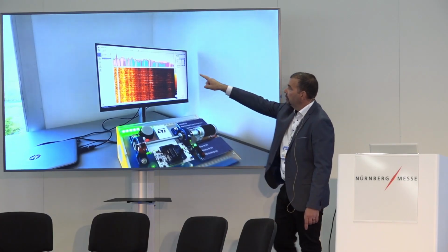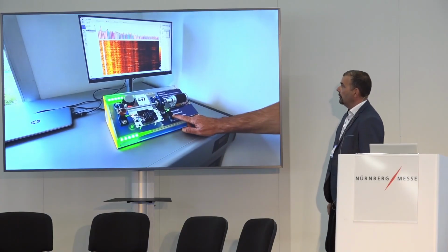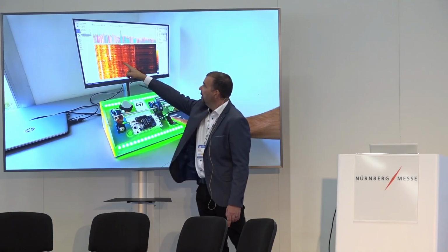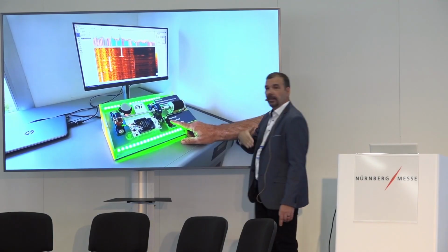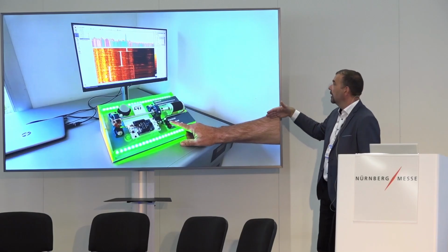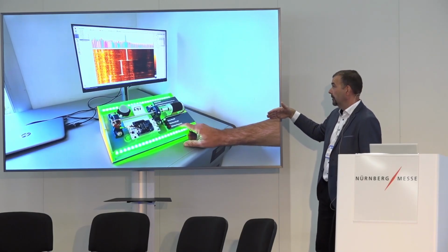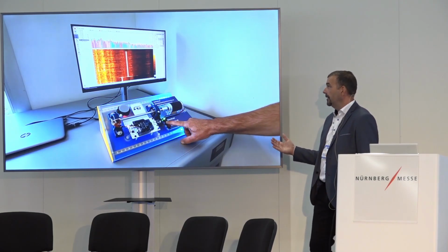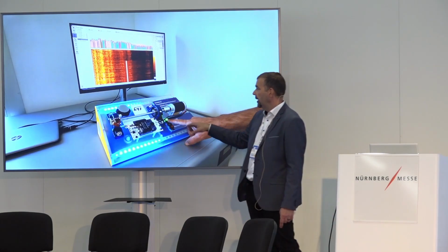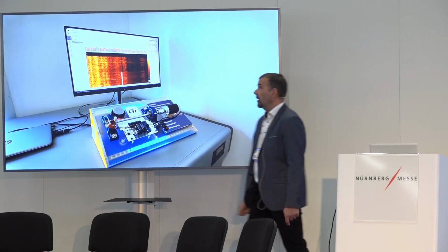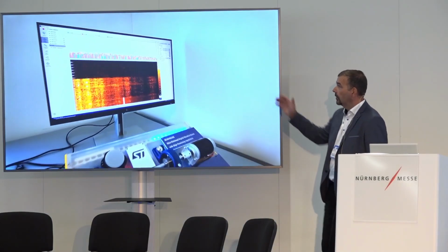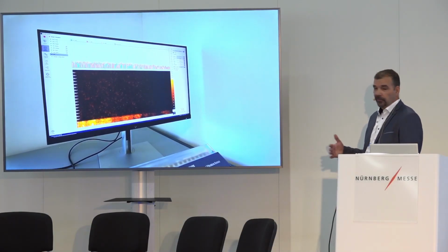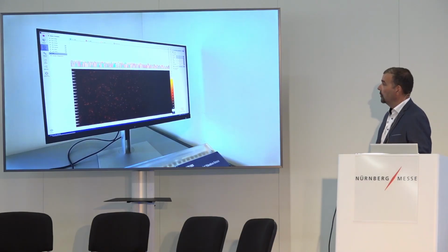The peak in the chart is showing the first vibration frequency, which I am now changing. And you can see in this spectrogram that the peak frequencies are moving as I am increasing the generated tone by the piezo actuator. What is the beauty of this? That you can run this FFT inside this sensor as well. So it's not only in the microcontroller or in the GUI I am showing here. And again, I invite you to come to our booth, and we can show it to you live.